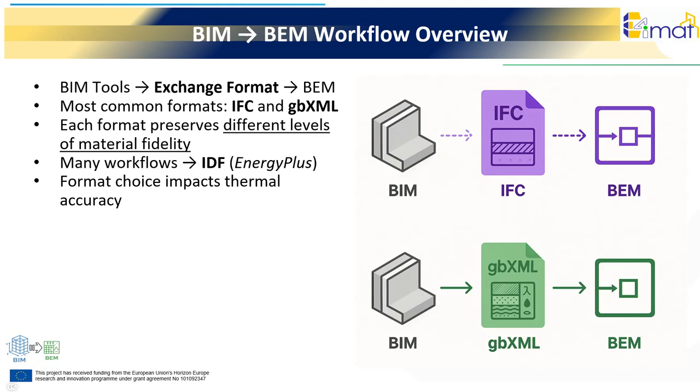IFC is widely used because it supports broad coordination across disciplines, while gbXML is more common in energy workflows because it was structured with thermal zones and constructions in mind. At this stage, what matters is not the technical detail of each format, that will be covered next, but the fact that they do not preserve material information equally.